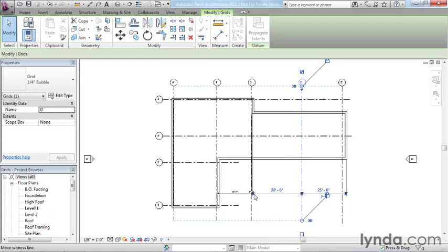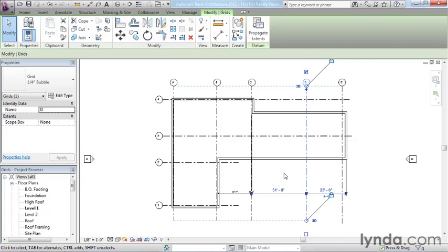If you click on the little square until it highlights and then start dragging it, okay, so I've still got my mouse pushed in, I've still got it held down, then highlight the nearby grid line and let go, it actually moves it to the grid line, and then I can type this number right here and put in 31 foot 8. Now the way that you do feet and inches is to put 31 and then a space and then the number of inches, 8 in this case. Revit will see that as 31 feet 8 inches. The alternative is to do 31 feet 8 inches. Both work, but I like the space 8 because it's a little bit less typing. And so both of those methods will work.